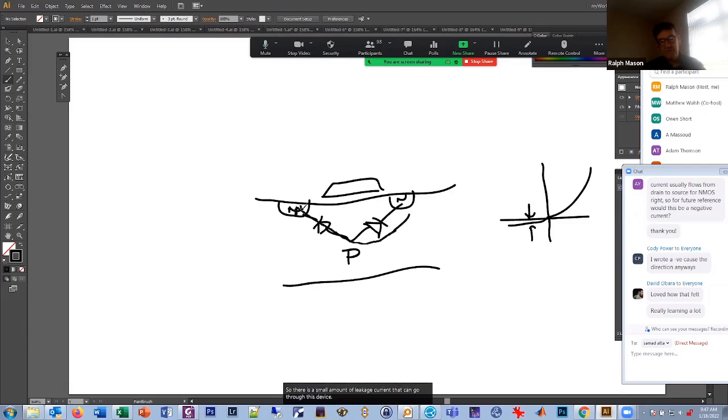And this one's forward bias. It's like picoamps of current, but it's important. We call this subthreshold because we haven't gone above the threshold voltage. We haven't turned the channel on, but there's still leakage through these reverse bias junctions. And so that kind of limits our minimum amount of current. That's a small amount of DC current.